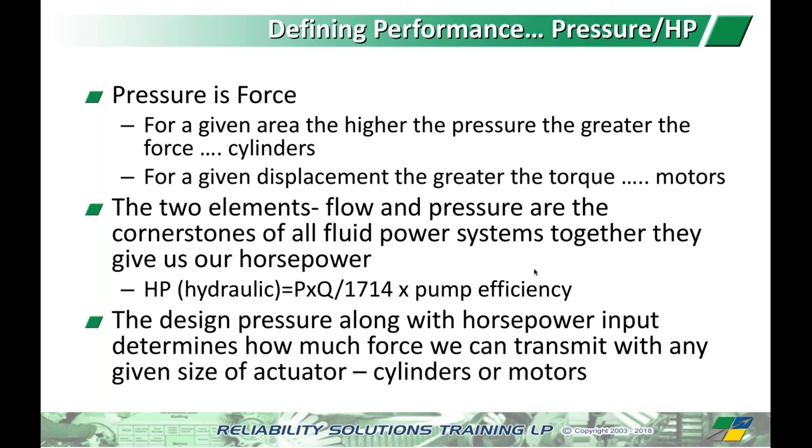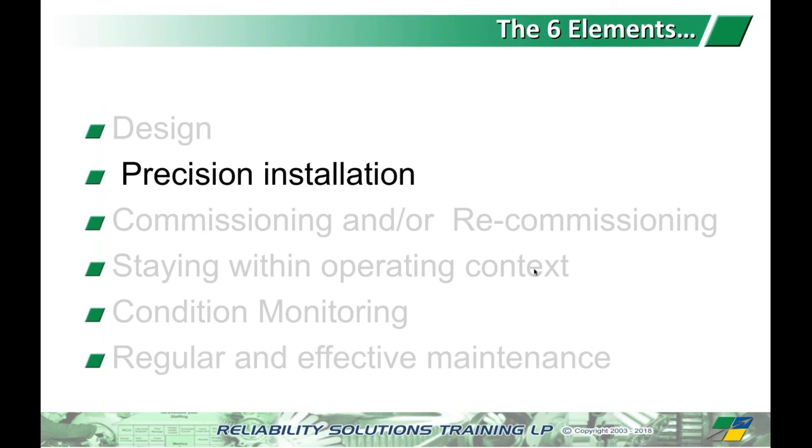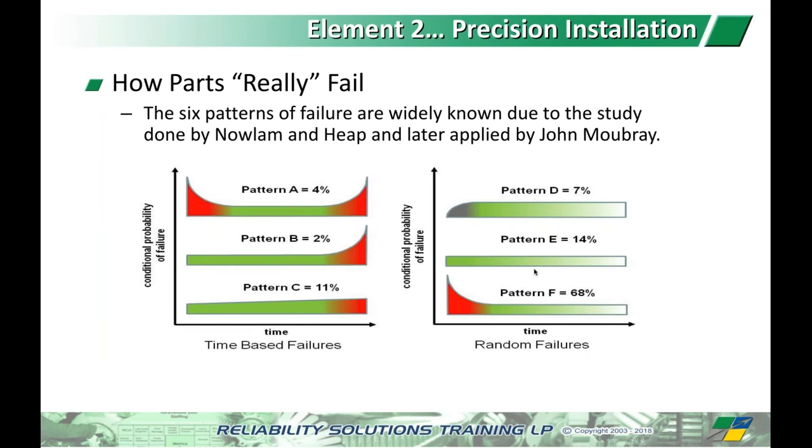And again, this is a way of assessing pump efficiency. If you know how many horsepower you're putting in, which you can derive from the amp load on the motor and the voltage and things like that, you can then calculate how much flow you're getting out or how much work is actually being done by the actuators, the speed at which they're operating and the volume of fluid you're moving. You then get an indication of how efficient your pump is.